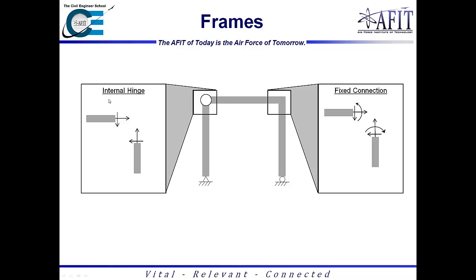When we talk about the internal hinge, we have to use the internal sign convention for it. And so the vertical force here becomes the vertical force here, and then the axial force here becomes the axial force here, or the X force there. Sorry, just trying to make sure I got this correct for you. But the idea is we need to make sure we're translating the loads appropriately. And as you could tell from the arrows, these need to be equal and opposite.